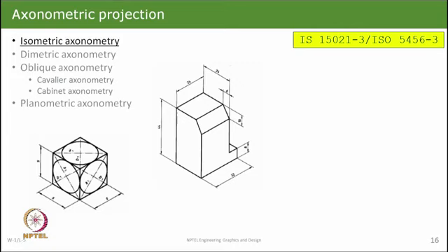It is in a way giving you the true shape, and the same object that we saw just now is shown in the isometric view, and on this I can show the dimensions. To show this length, we draw two lines which are called extension lines, then we put another line which is called a dimension line, we put arrows at both ends and write the number there, which is the size of this line, the length of this line. So, that is very quickly how you put a dimension on a picture.